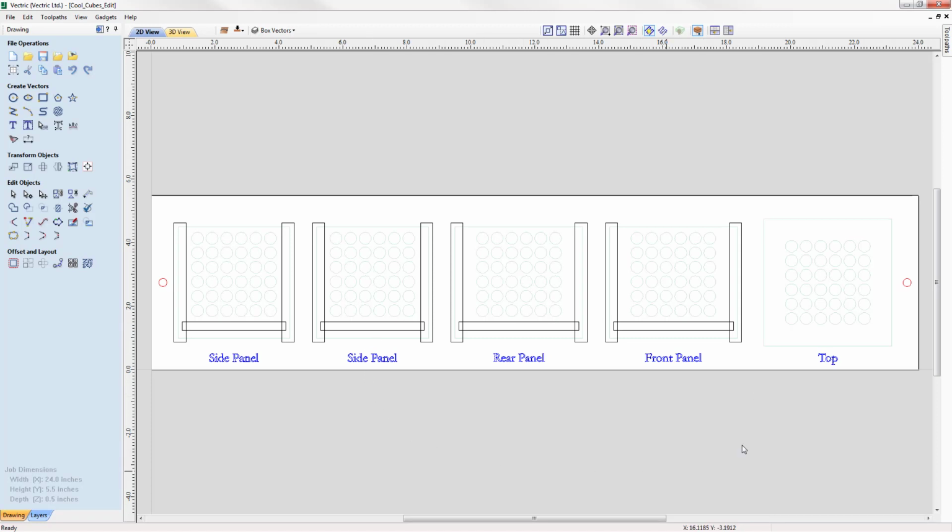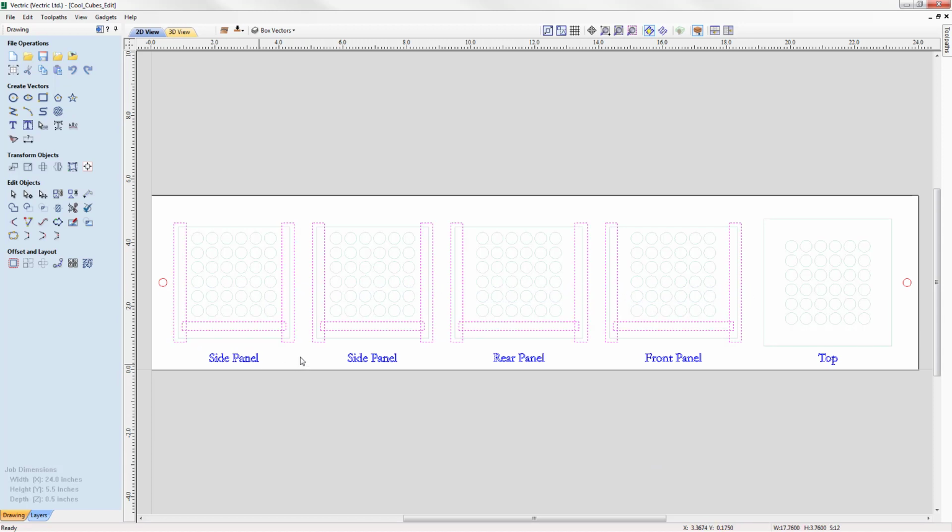So now I want to run through how I plan to cut the whole part. So in terms of machining, I plan to cut these vectors using the pocket toolpath so that we can assemble all of the panels to form the box. Then we're going to look at taking this vector here along with this vector here, and we're going to machine the dowel holes all the way through the material and into the spoil board. And that's all of the toolpaths for the top side.